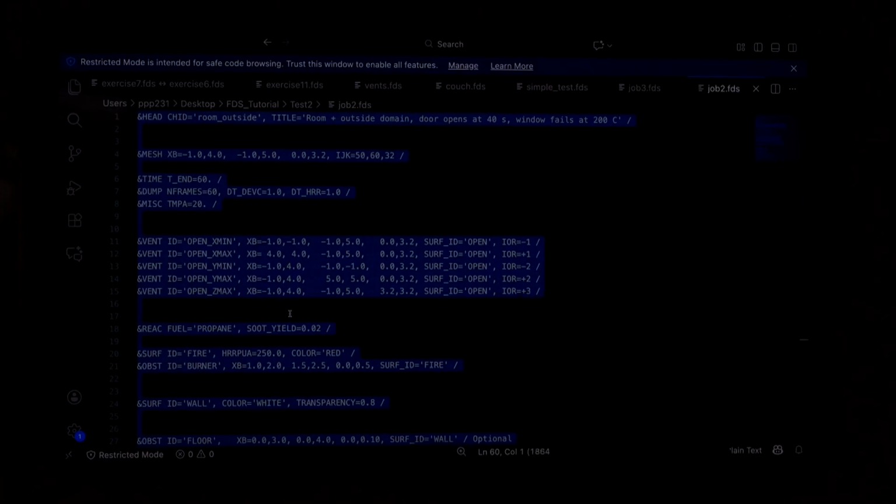If you compare these lines with the previous code, in the previous code there was no soot, because you have propane. Propane burns clean. There is no smoke created, right? But for the purpose of the demonstration, I added the smoke so that you see how the smoke is getting out of the windows and the doors. So if you know that your fuel is not clean or doesn't have oxygen for complete combustion and it is going to generate smoke, then you can add the soot.